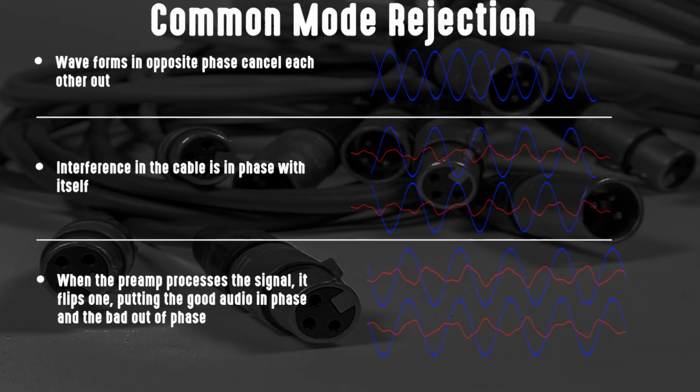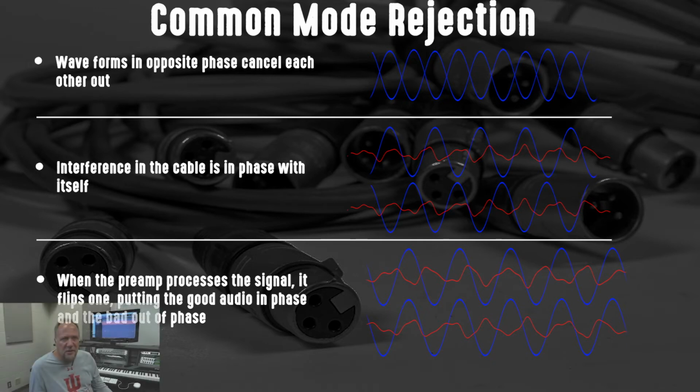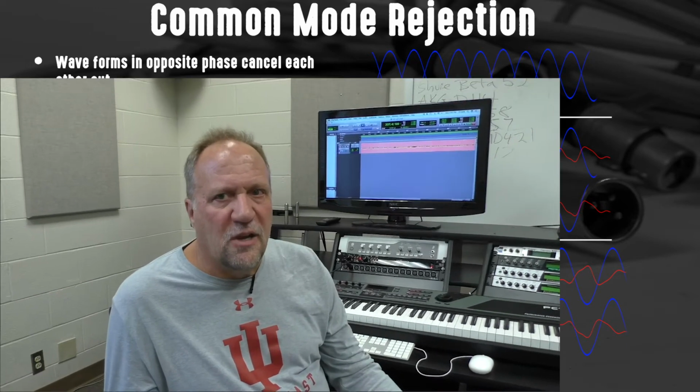Therefore, what's called a balanced signal, that uses two signal carrying conductors and a ground, is the most robust and the least likely to get interfered with by the nasties out there in the world. That's the ideal way to transmit, particularly in high RF type environments or over long cable runs.